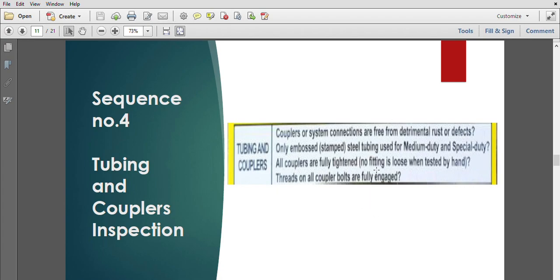So for couplers, sometimes we inspect them prior to the erection. Sometimes the nut is not rotating, so reject it. Sometimes, for example, a swivel coupler is stuck, it cannot be rotated, so reject it, do not use it. And some couplers are also rusted. If the condition is not good, then remove all from site and replace them with couplers in good condition.